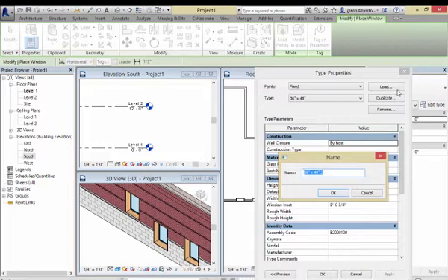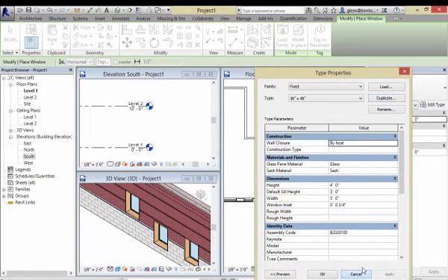So be cautious when you're changing these things. If you're making something just for yourself, especially if you're working in a team and other people may already be subscribing to and using that type, be cautious about changing it. If you really need to change, it's probably better to duplicate, to make your own version of it and then customize the duplicate.